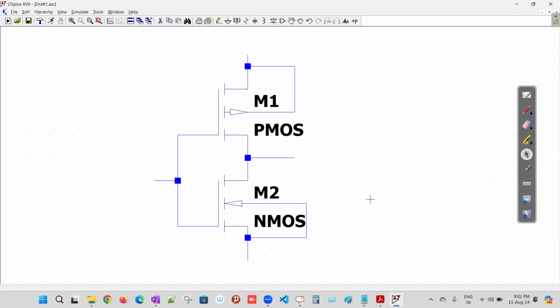Now what you have to do is go to this label net and click there. Let's name this input as A or Vin. So Vin. And here, do not pick anything like port type, input, output, bidirectional. Don't touch them. Just none. Okay. Now click OK. So this one, you just place it here on the wire, then click.